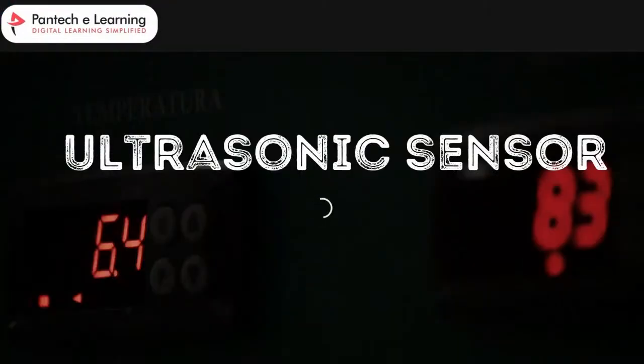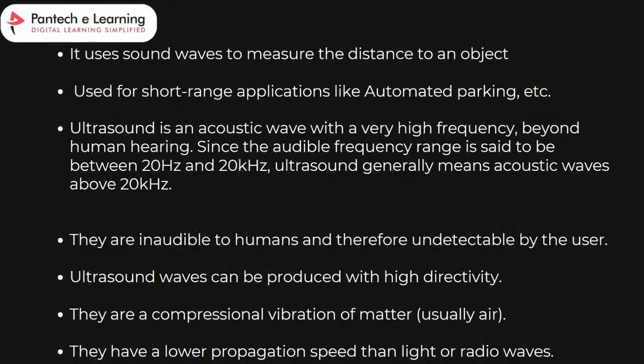And we will discuss the ultrasonic sensor. So what is an ultrasonic sensor? Ultrasonic waves are sound waves with frequencies higher than the upper limit of human hearing, typically about 20 kilohertz. These waves are used to measure the distance to an object by sending out sound pulses and measuring the time it takes for the echoes to return. This method is known as ultrasonic ranging, or sonar.